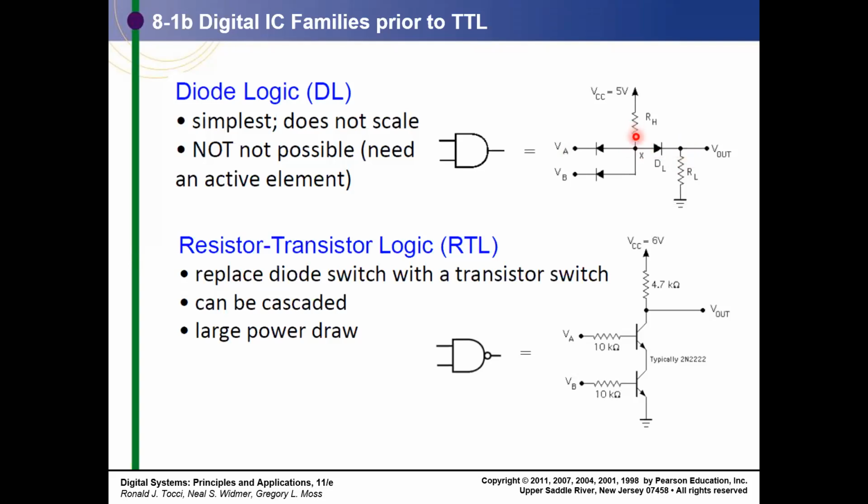Because this is the low resistance path, it will drain from this. This is a higher resistance path, so everything gets sunk and this becomes a low node, 0.7. Therefore this node will not reach a high voltage, it will reach a low voltage, and the low voltage value depends, but not higher than one diode drop.